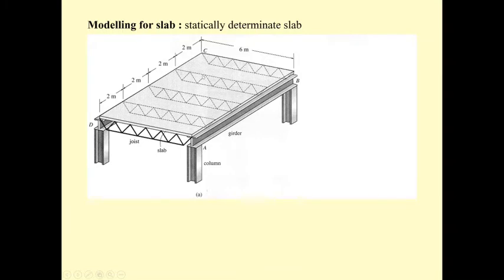Since the joists separate into inside joists and outer joists, the outer joists will carry a smaller area compared to the inner joists. So that means the outer joist carries less force. The inner joist is going to carry a large force. And then, since the girder will carry the reactions from the joists, this girder will carry 1, 2, 3, 4, 5 loads. And the load at the end, at A and at B, is going to be smaller than the load due to the inside joists.